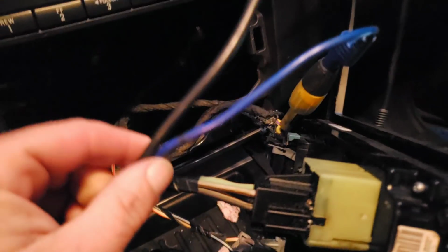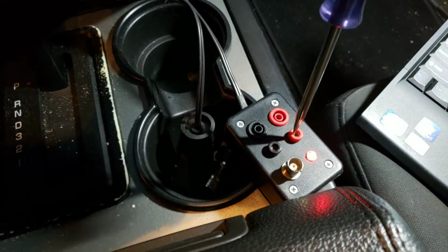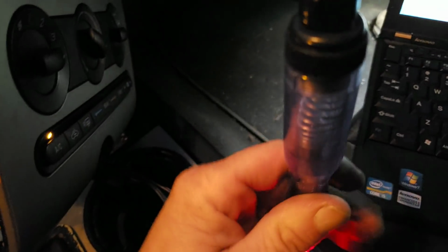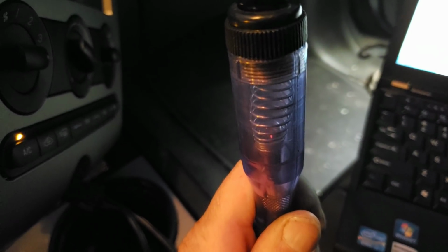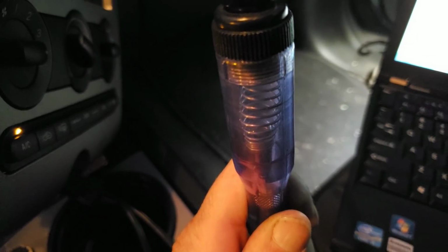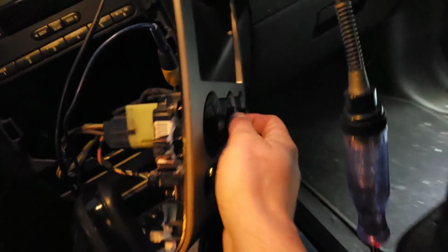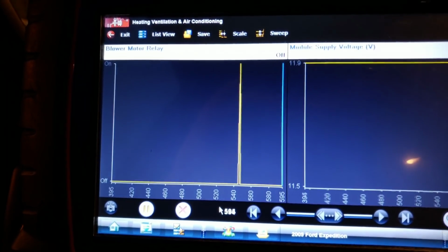That's actually what I'm back probed into, and I'm watching that wire. I'm tied into a power here, and so I'm watching to see whether or not it ever gets grounded. And as you saw a moment ago, you'll get that momentary blink like that, and there's no good reason why that's happening, but also, if I sit here and I change around the blower switch, if I do anything at all with it, there's no change.